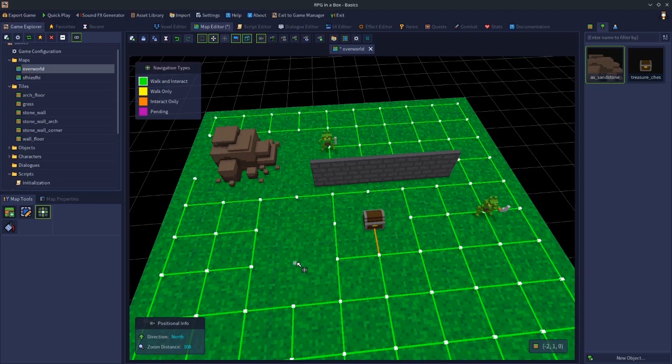Whereas the right mouse button and dragging the mouse will just follow the line where you drag your mouse. So it's a finer deletion. If you just want to delete the navigation entirely, then you can just click the delete key over these points. So those are the 2 ways of deleting navigation. And you would just place navigation by clicking and dragging with the mouse key.